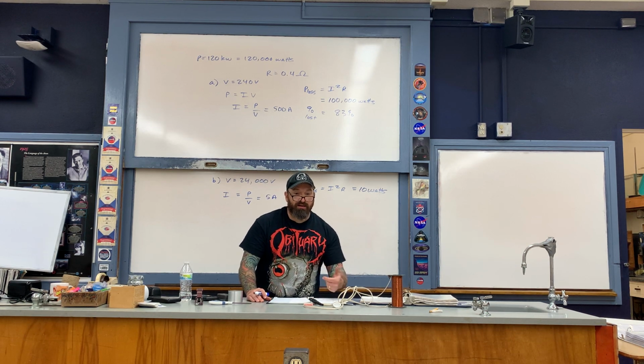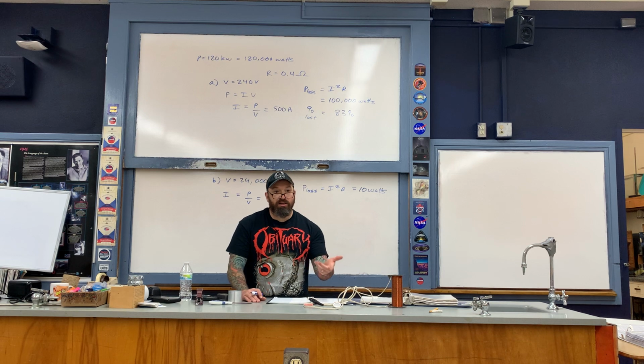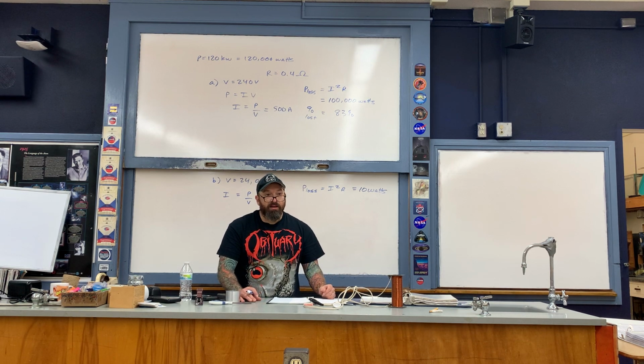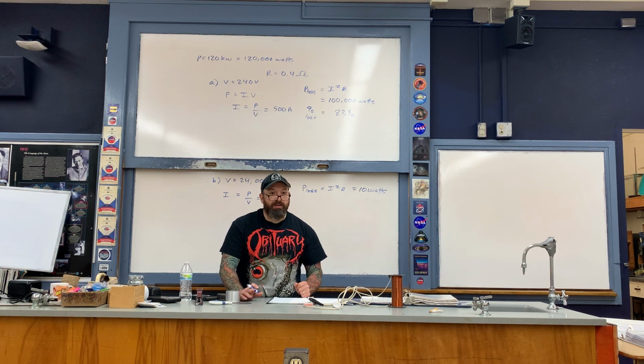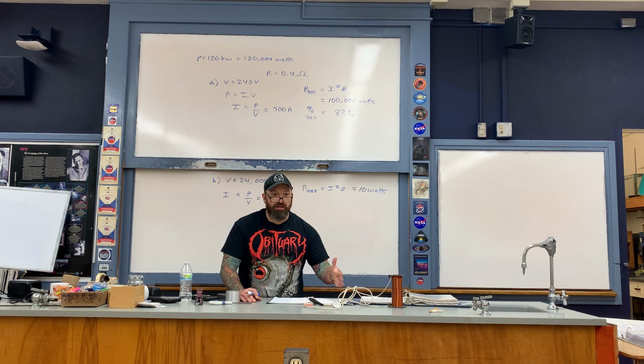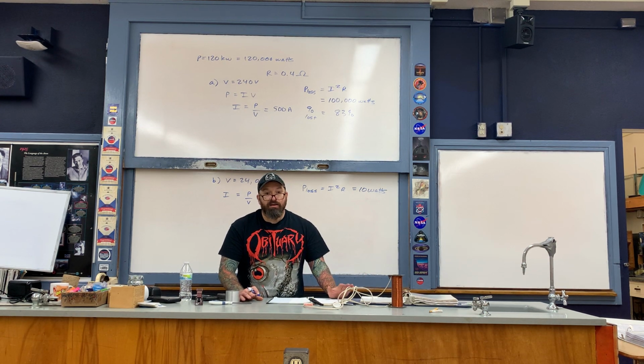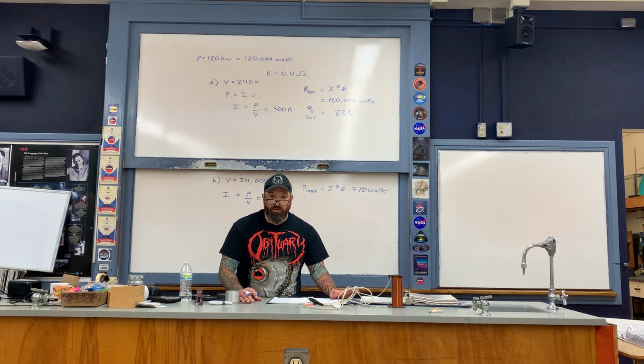They eventually send that out, for example, to the city streets and the residential streets as well. The last step of stepping down the voltages to low values that you would then get in your home, 120 volts as the VRMS. That last step is a step-down transformer that is housed in a gray cylinder that you may have seen, for example, mounted on an electrical pole right next to your house. That's the last step-down transformer prior to the power being directly delivered to your home.